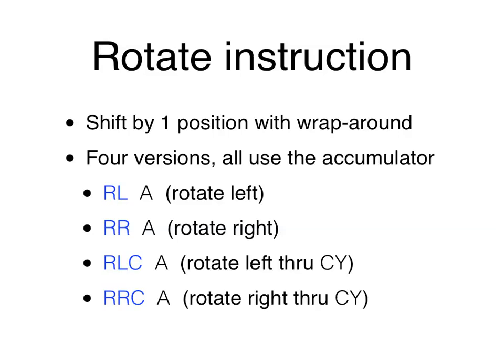Okay, so I'm going to continue with the 8051 instruction set. Now, these are rotate instructions. There's rotate left, rotate right, and rotate left or right through carry. I think I mentioned this before. Rotate means it's like shifting, except the bits that fall off come in on the other side.